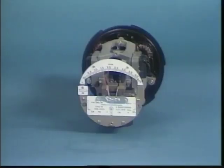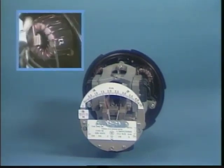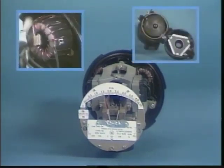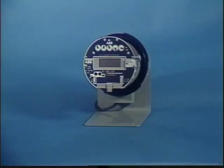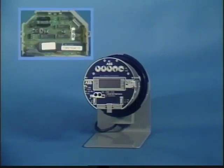A second type of demand register is the thermal demand register, which uses small transformers, heater elements, and bimetallic coils. The third type of demand register is the electronic demand register, which uses an electronic microprocessor. Each of these demand registers is associated with a particular method of responding to and indicating demand.